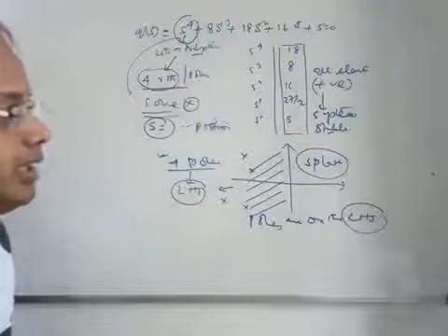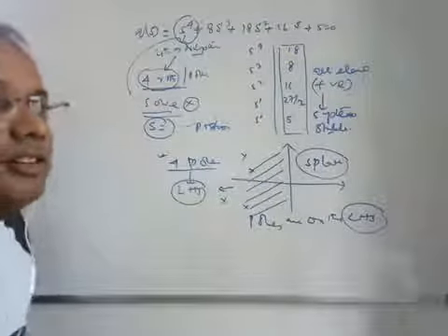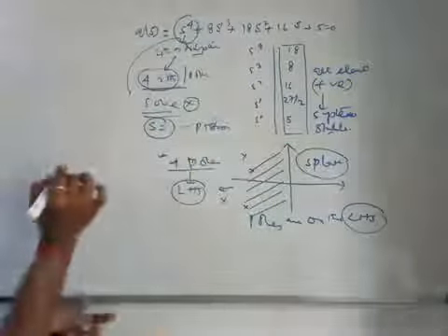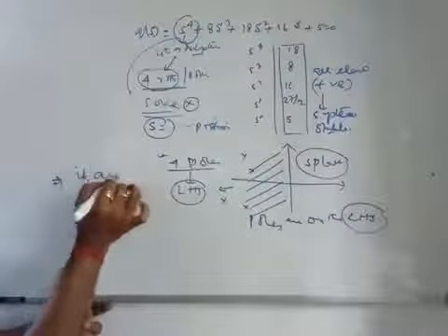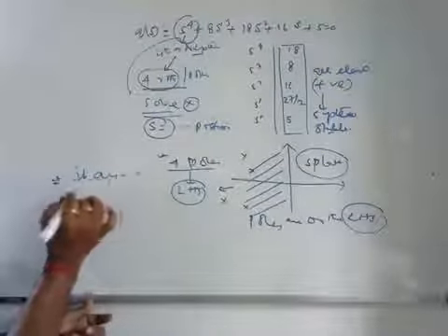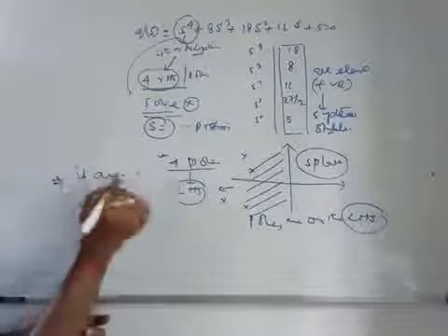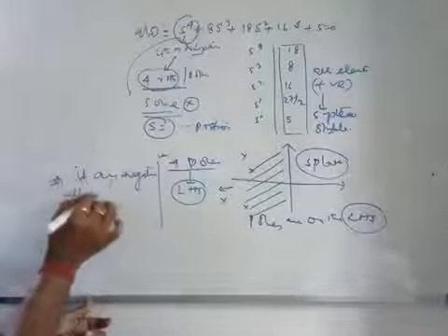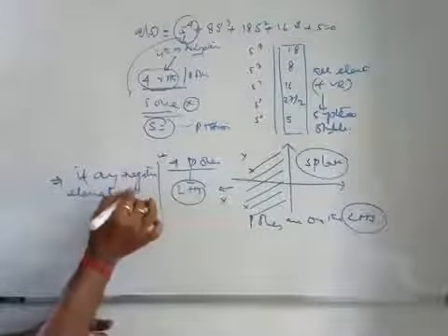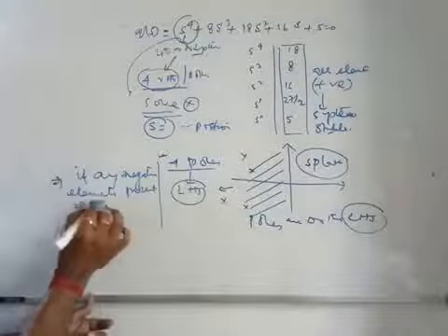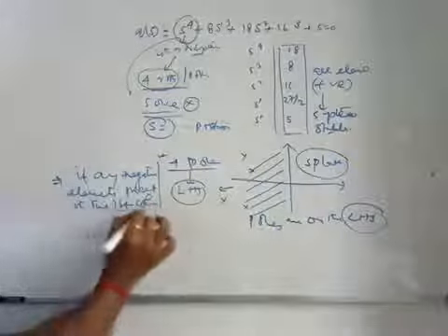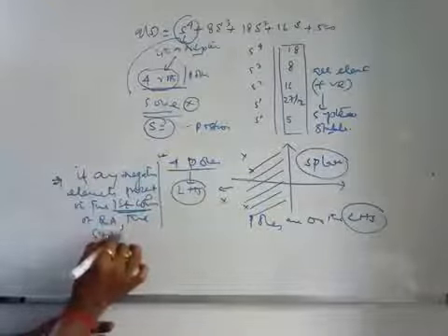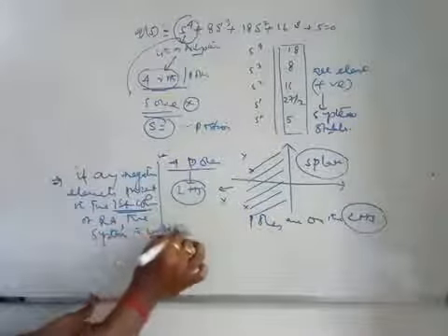If it so happens the system is unstable, then how can it be explained by using the Routh array? That means if any sign, or you can say any negative element is present in the first column, very important, first column of the Routh array, the system is unstable.